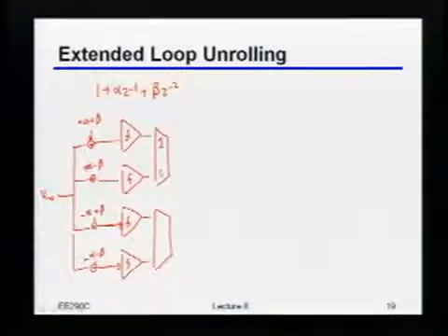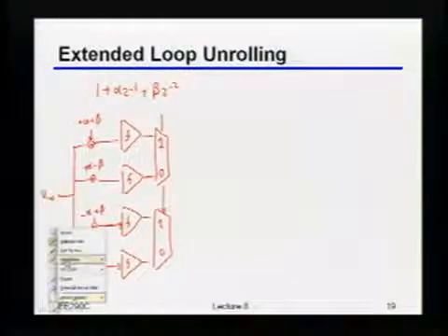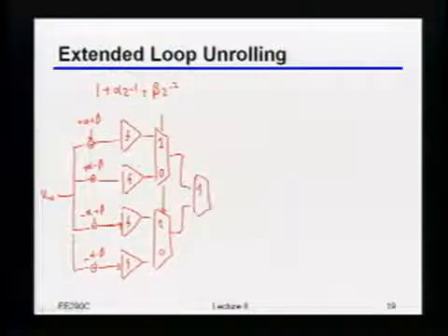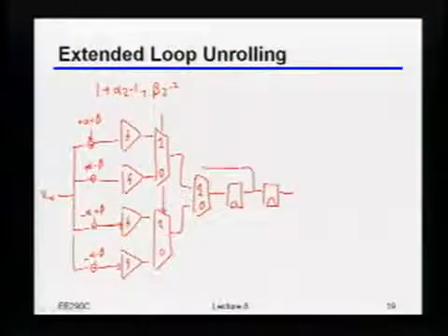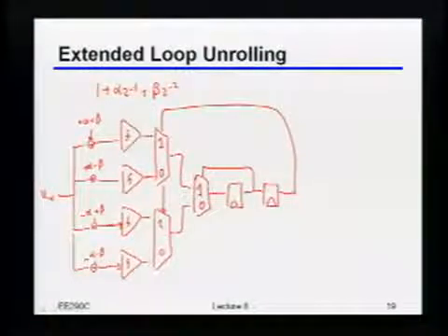Right, so as an example, in this case, based on the bit that's going to be 2 periods ago, I'm going to select, for both of these, whether I choose the upper comparator or the lower comparator. So in other words, if the bit that was 2 bits ago was a 1, then I have a plus beta, I have a plus beta. Right? And then, of course, as this should hopefully be obvious, I'm going to have yet one more multiplexer here that looks like this. And now I can actually close the loops. Right? So this one would choose the bit immediately following. And this one would, of course, choose the bit from basically 2 clocks ago. Okay?